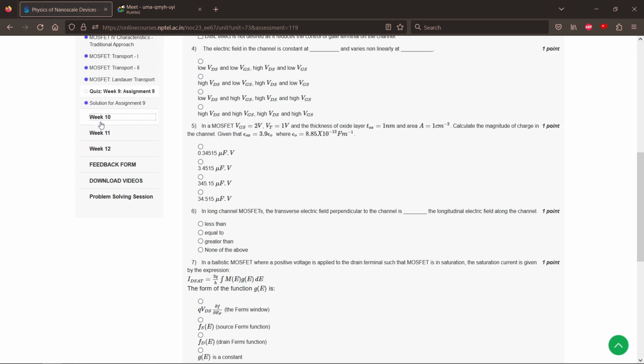If you remember, we did the de Broglie wavelength calculations in our previous discussion sessions. You were there for that. So we saw that the de Broglie wavelength for typical electron kinetic energy values comes to be around 15 to 20 nanometers. So something in that range, ballistic transport is still good. Yes, Intel and a whole bunch of other people are working on the 5 nanometer domain.